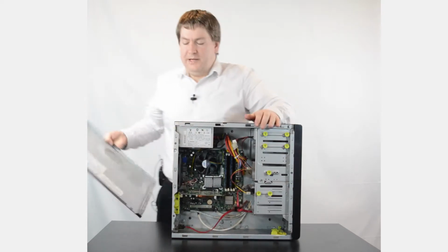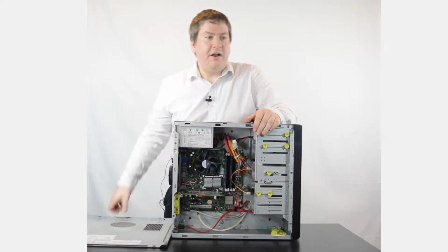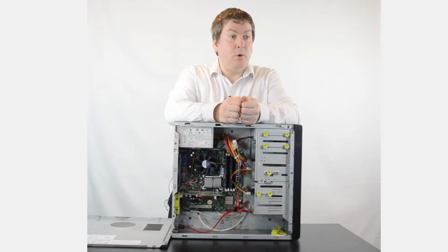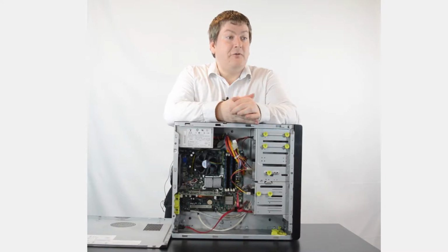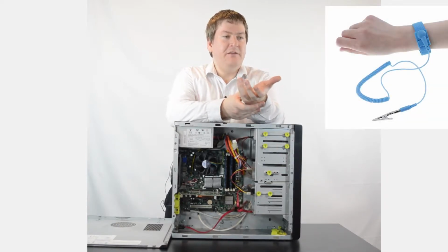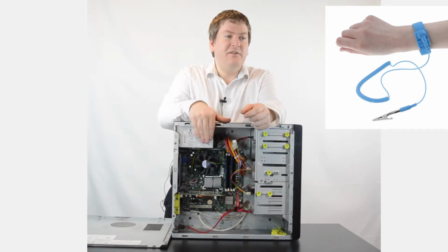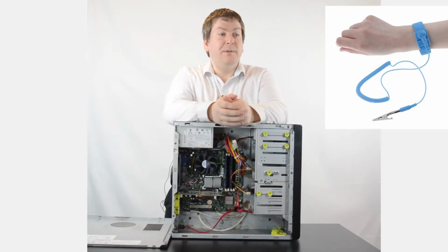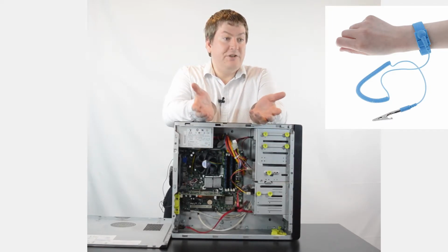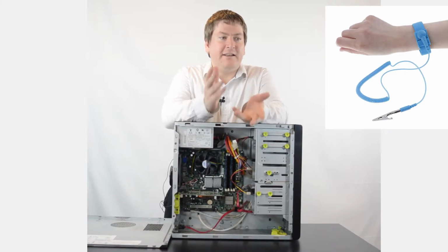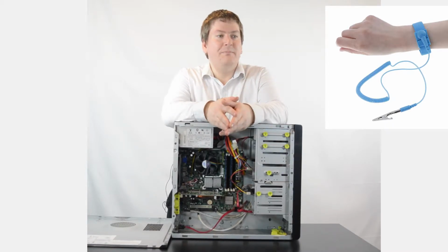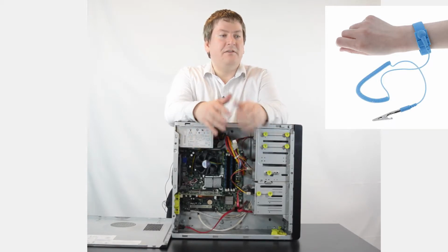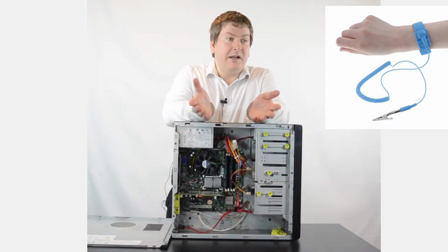So one thing I should mention is if you're ever opening up a PC like this at home, you should use something called a static wristband. What these do is they connect to your wrist and then to the case or some kind of grounded source, just because on your own PC you don't want to damage it. If you have static electricity, like from rubbing socks on the carpet, you could zap one of these components and it's not going to work again.